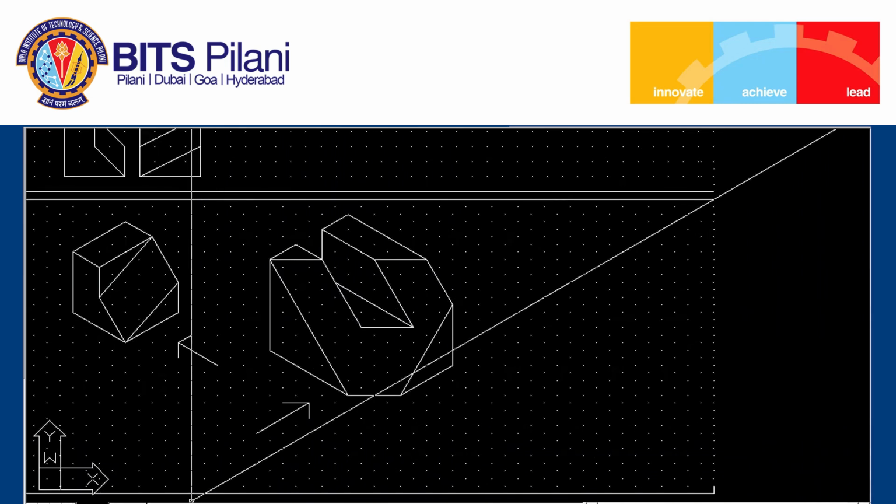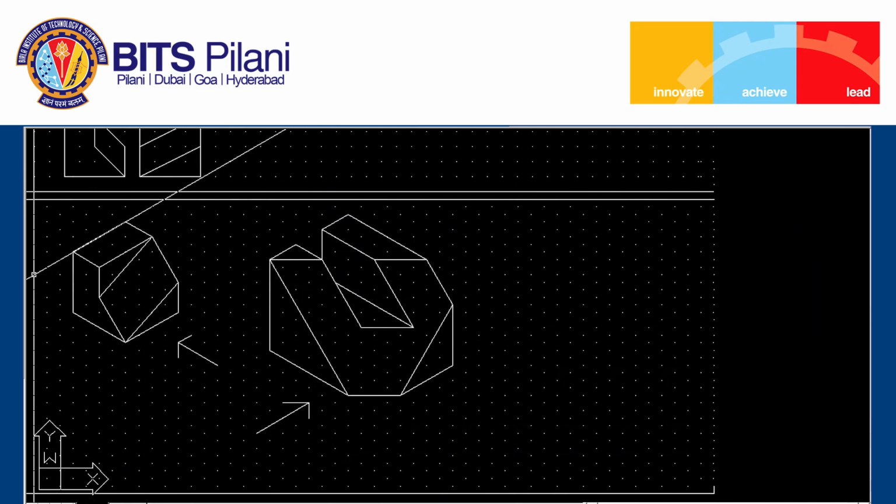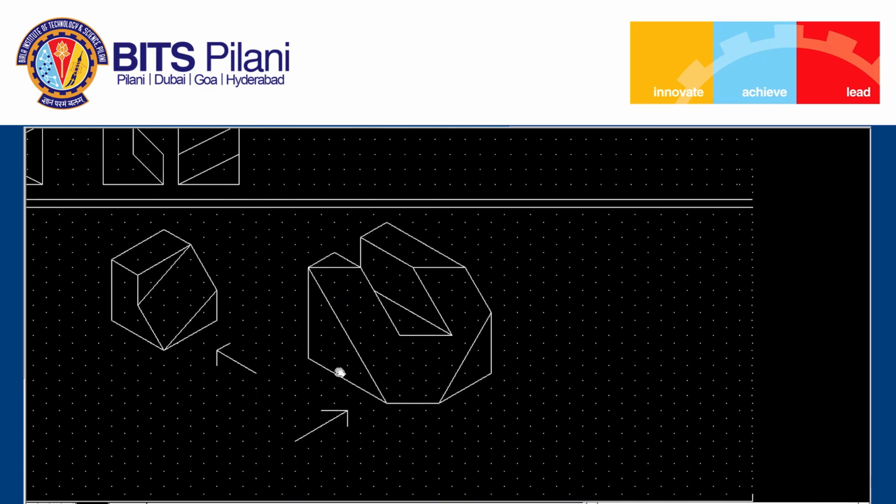Let us discuss the third problem, which is shown, and for this problem the direction of the observer to see the front view is given with the arrow. In this problem I can see we have principal surfaces as well as a skew surface, and we will see how to solve such problems. So, here we can see the front view, top view and the visible side view, which is the right hand side view. We will follow the third angle method of projections to draw the orthographic projections for this particular object.